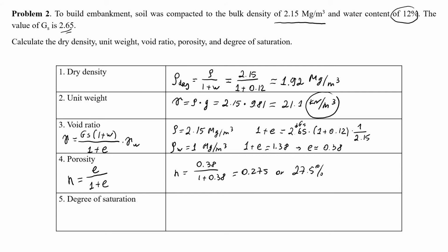For degree of saturation, there is a very good formula. It's given as this one. It's water content times specific gravity divided by void ratio.